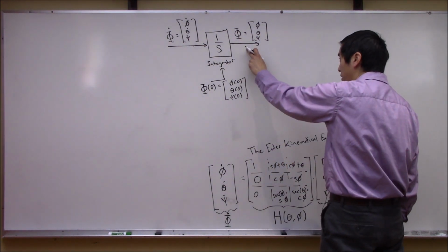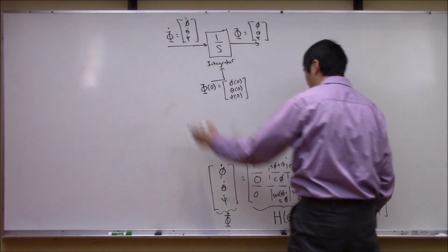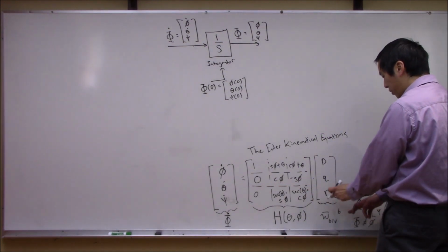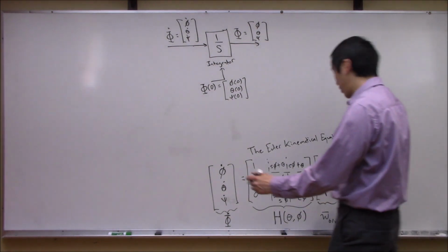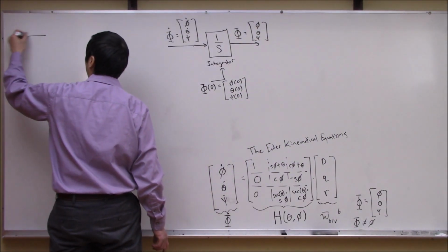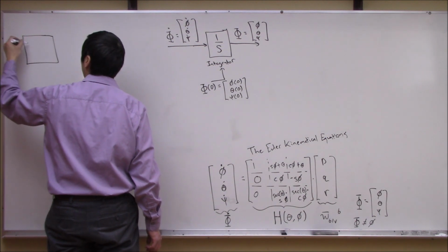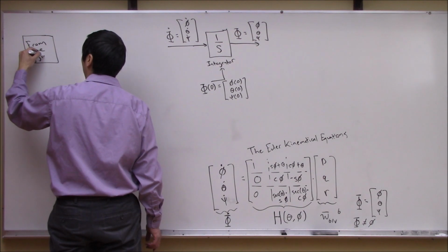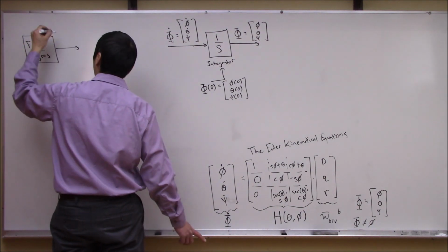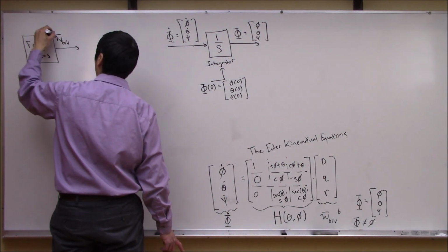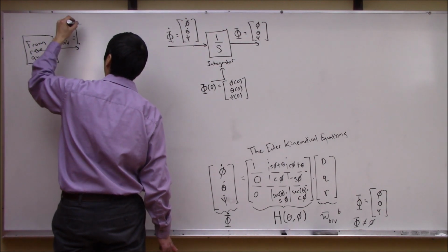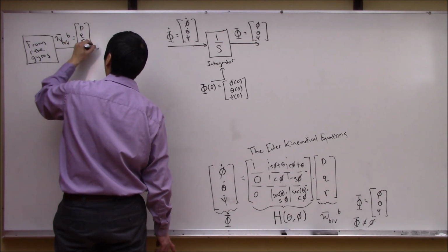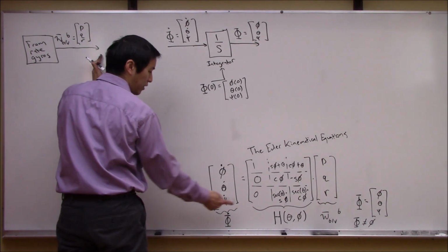Now, if you have this, I need to be able to calculate phi dot. Well, that's exactly our equation over here. So let's assume that maybe you've got the rate gyros spitting out data here. So maybe this is like some data source. This is from rate gyros, right? So coming out of this, the rate gyro is going to spit out omega b with respect to v expressed in the body frame, or it's going to give you a 3×1 vector of p, q, and r, right? Okay, so now the mapping between here and here, it's just this H matrix.